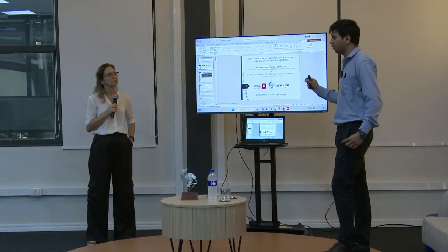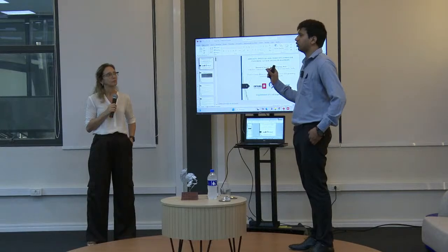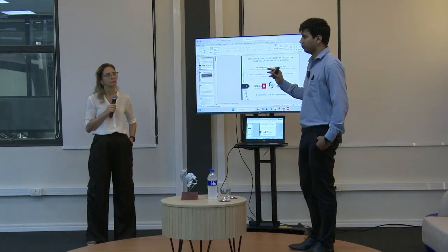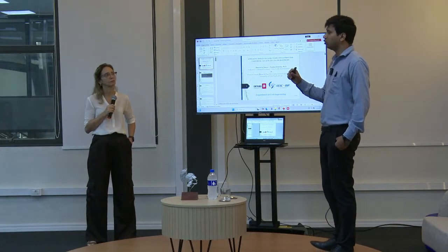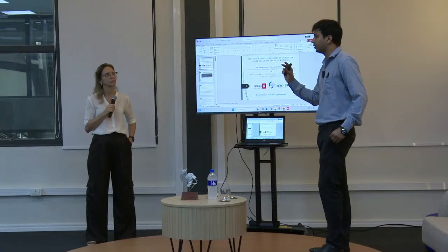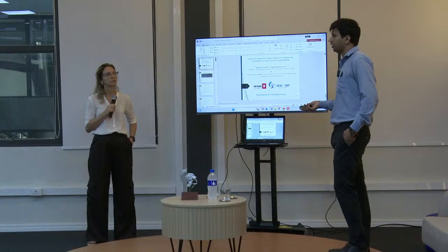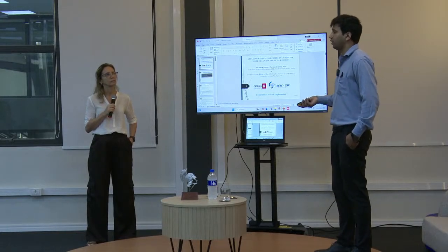If we use a bit bigger diameter for the nail, normally the diameter varies from 30 mm, with a maximum shaft diameter of 80 mm. So if we use a bit bigger diameter with a hollow section, we can apply injection to the helical soil nail also.